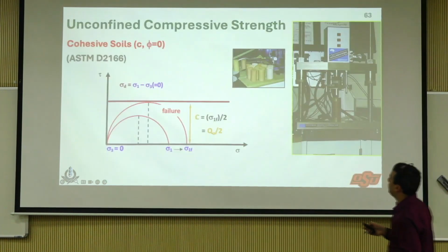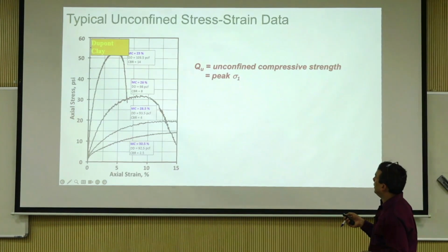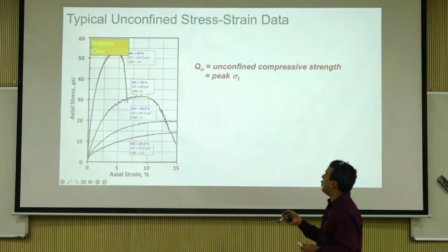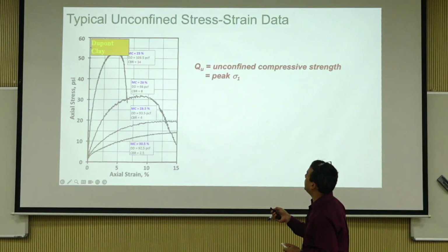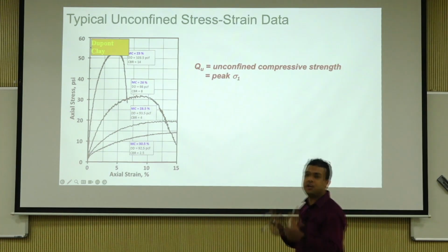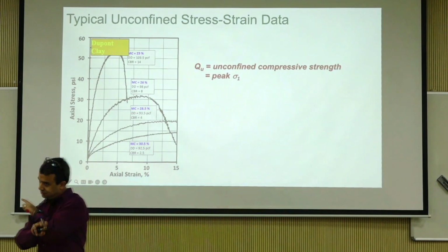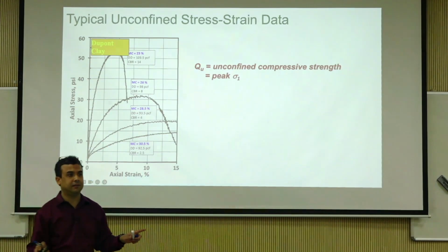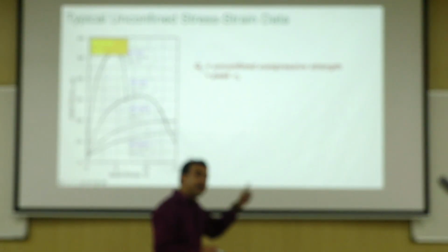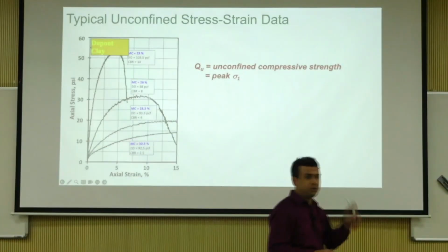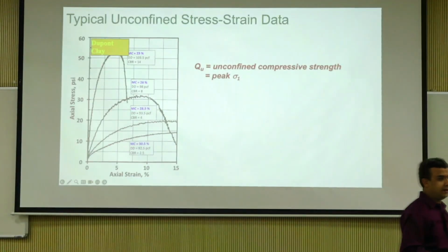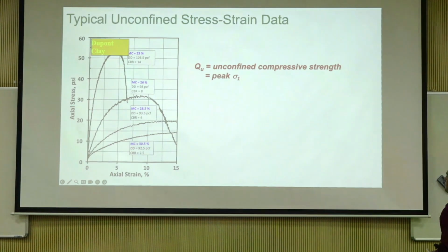This is just some examples of how moisture content and dry density affect that. So moisture content is 23%, 26%, 28.5%, 30.5%. Your biggest enemy for soils is water. Just live with it, right? No matter what you do to compact, no matter what you do, water is going to ruin you, right? That's just one of the things. So this is just one example.